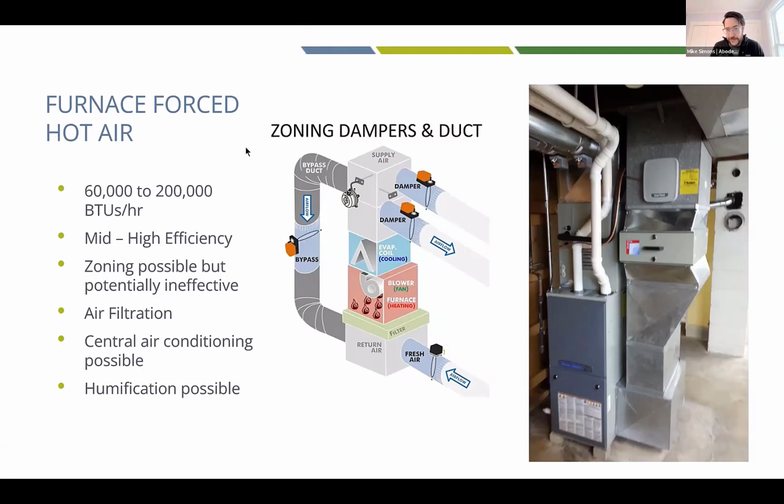So we're now seeing our first high efficiency system, and how I know that it's high efficiency is that instead of a metal vent pipe, it's a plastic vent pipe. If you were putting 350 or 500 degree gases into a plastic vent pipe, it would instantly turn to goo. So this is high efficiency. Other things I see over here is ductwork on this side, and that's the return ductwork that's sucking the air back in from the home.